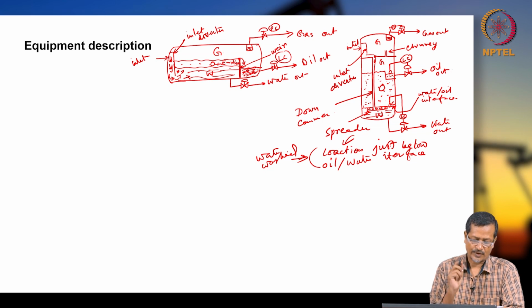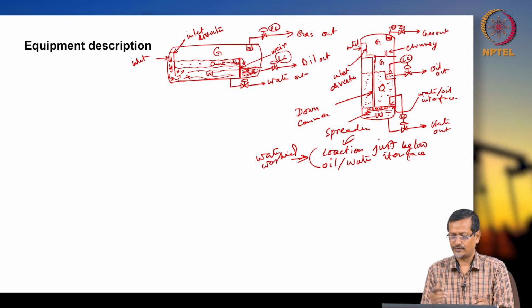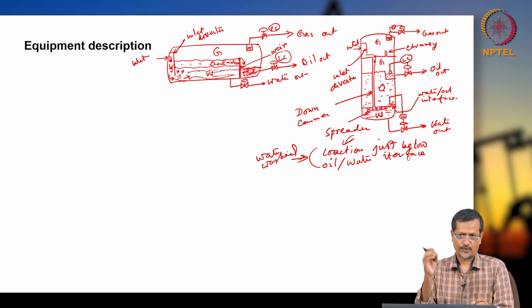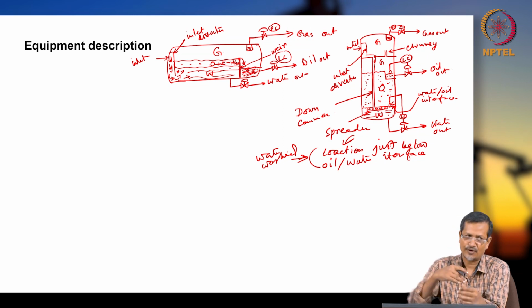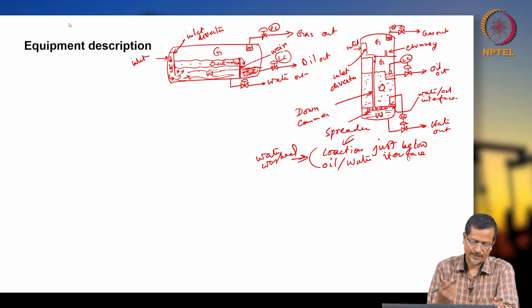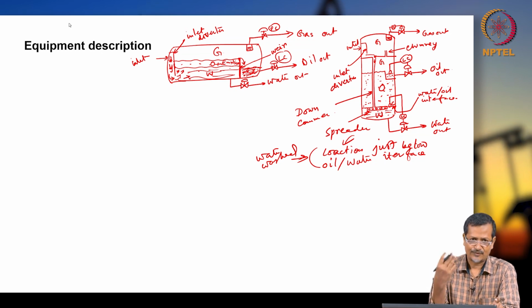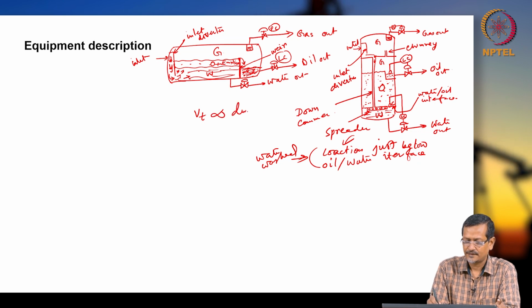So water wash is the coalescing of water droplets. If there are lots of water particles, when they come into the water area, a water particle will get more water, so it will create a bigger particle. When a bigger particle is there, it will not move up, rather it will be staying there. Okay, so that way you are creating a bigger particle, and you know the settlement formula Vt, right?